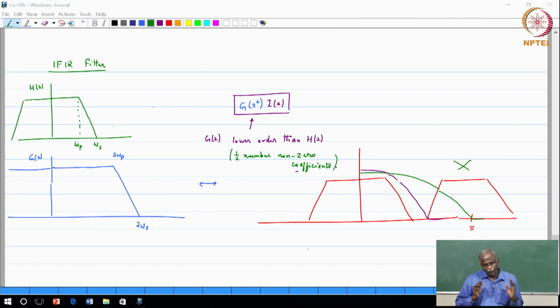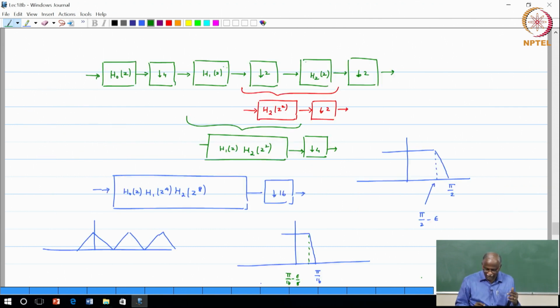right. So what have we done? We have obtained a tool from multirate signal processing which says that when I do noble identities, I can move the blocks around, and actually I get an advantage because my spectrum gets compressed whenever I move them, when I get a filter of the form H of Z raised to some power L.